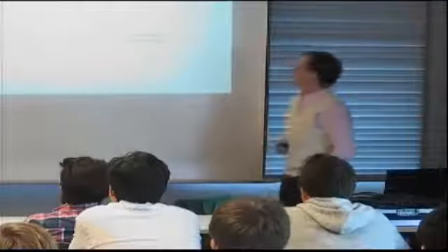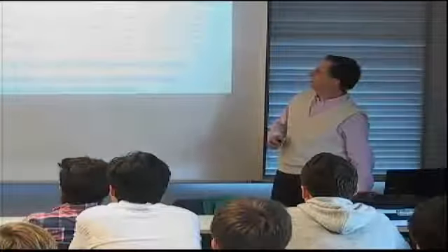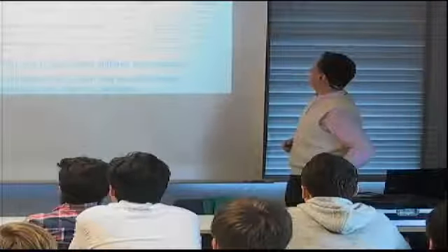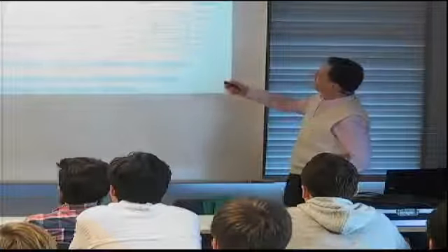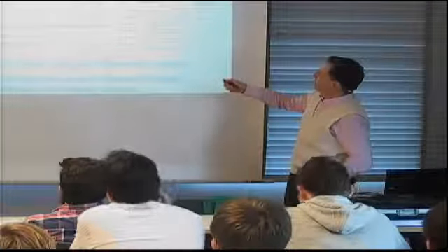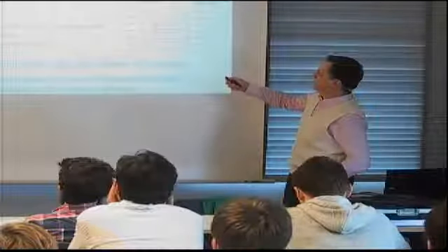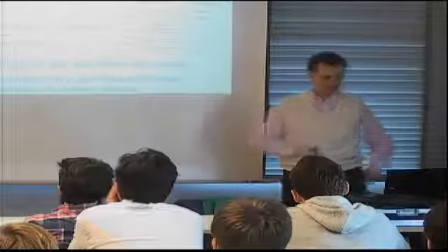So, for the stacking sequence shown in the previous slide, where is my stacking sequence? Skin layup. Oh, don't worry about the skin layup. Okay, here it is: 45, minus 45, 0, 90, symmetric with an overbar, which means the 90 does not repeat about the mid-plane.